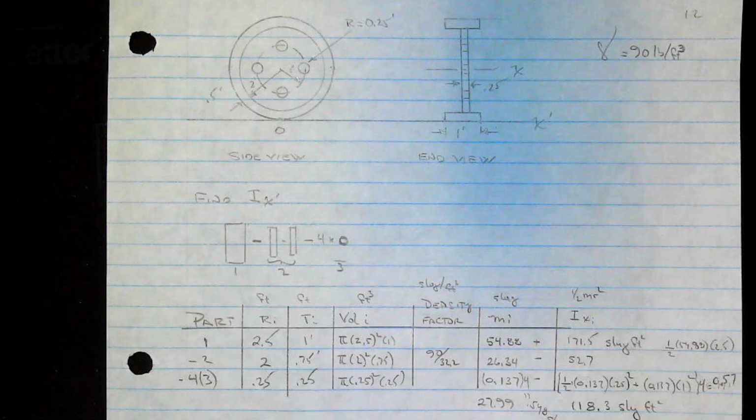It's very straightforward, but let's just think what we can do now. All of these, this, that, and the one that was cut away, are all centered. Their center of mass goes along that z. So we don't have to do any parallel axis theorem, moving anything from its initial center line over to the z1 axis. They're all lined up, so I can compute mass moment of inertia for z1 directly, and that's this equation.